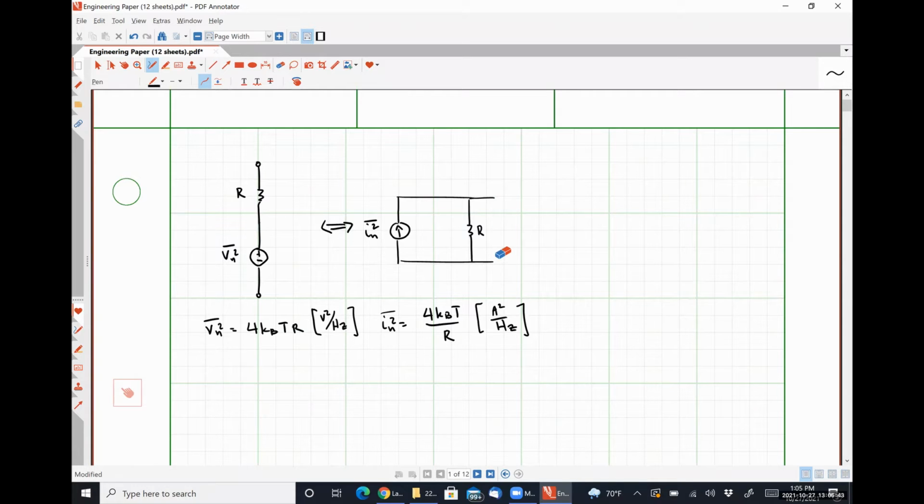So if we were trying to employ traditional Thevenin and Norton equivalent circuit techniques, we could say that this open circuit voltage here should be exactly equal to Vn squared, right? Well, we get that by saying that it's going to be In squared times R, resistance, squared, okay? So instead of just converting by using the resistance, we have to square it.